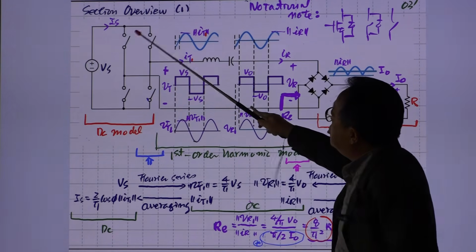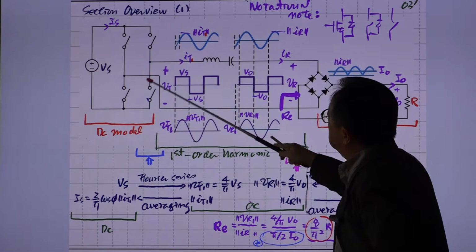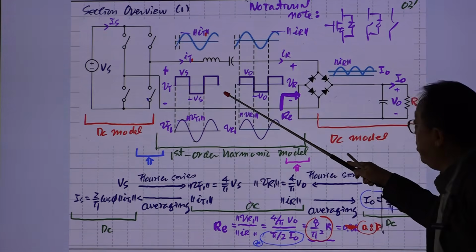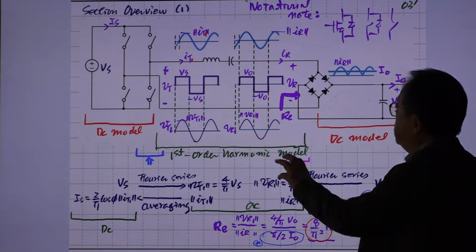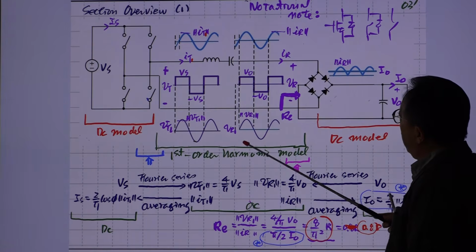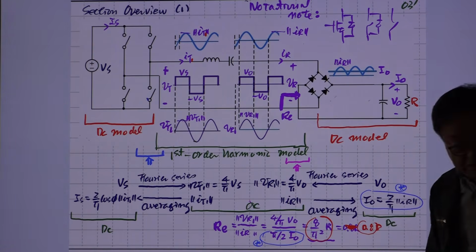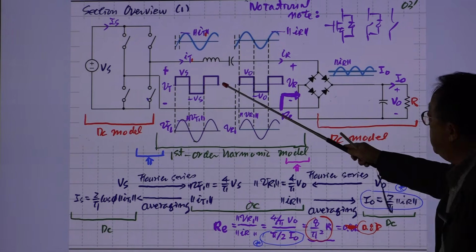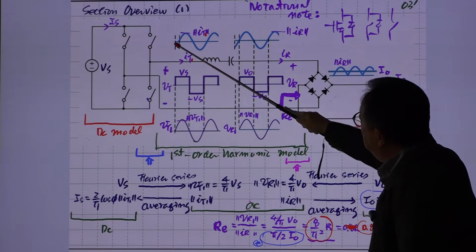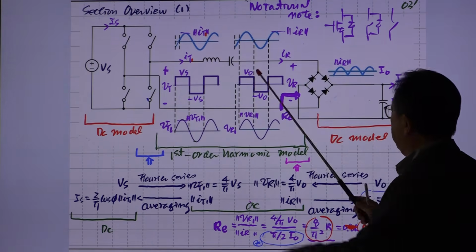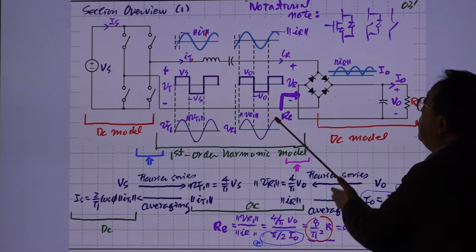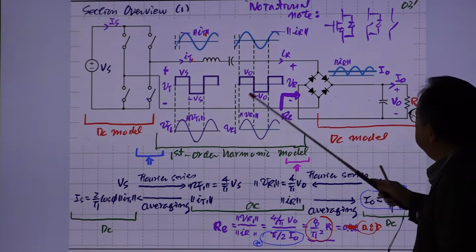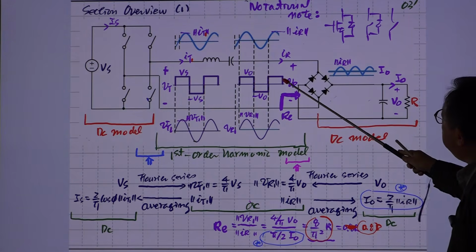With the switching function of this full bridge network, this voltage is transformed into square pulse waveforms, and with a high Q tank circuit, the tank responds only to the fundamental component of these rectangular waveforms. It will generate current like this, with some phase delay in between, depending on the operating point of the converter.